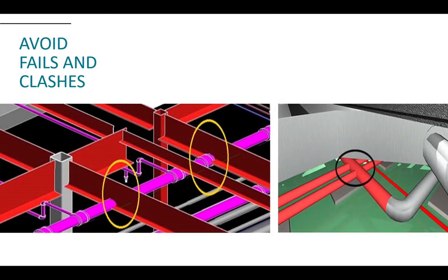So in this slide, we can see a kind of output from that software called Navisworks we're using. Conflicts and interfaces between different components and different design teams can be identified and resolved through the use of this software. On the left-hand side, we've got a structural model and a plumbing model. We put the two models into Navisworks, and it's detecting that there's a pipe going through an I-beam. So this is an issue, and this can be detected on the model as opposed to on site.